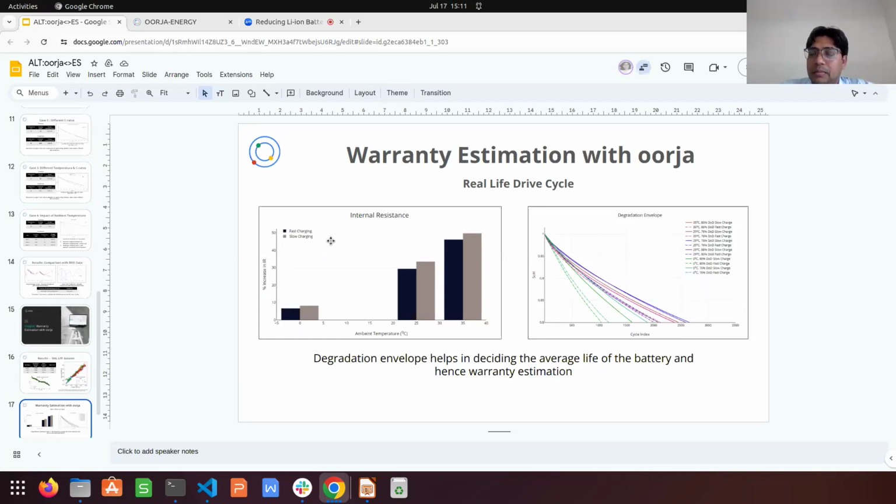So sometimes this 300 cycles of data is not enough for predicting the knee points, because a lot of things happen in the cell much later. So what we also try to do is mix the physics-based training data up to 300 cycles together with some tests where we have seen the knee points with the hybrid model.